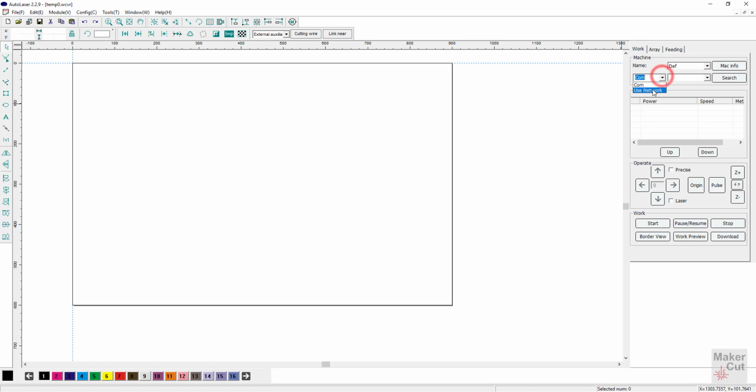If we do change this to use the network, it's going to do a search on the network looking for 192.168.0.100. This is the default configuration for the machines that come with a Top WSM controller in them. And if your network uses that IP address, then you should get a connection at this point. Since I don't, and I wanted to show you this, you'll get a link error.